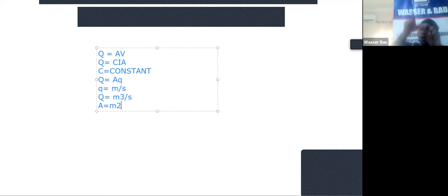So the protocol and the process of getting your Q is important. Once you get your Q, the problem is solved. Because with your Q and your slope and the return period, you go to many charts on the internet, and you size your pipe. Then after sizing it, you detail it. That's all. Job is done.